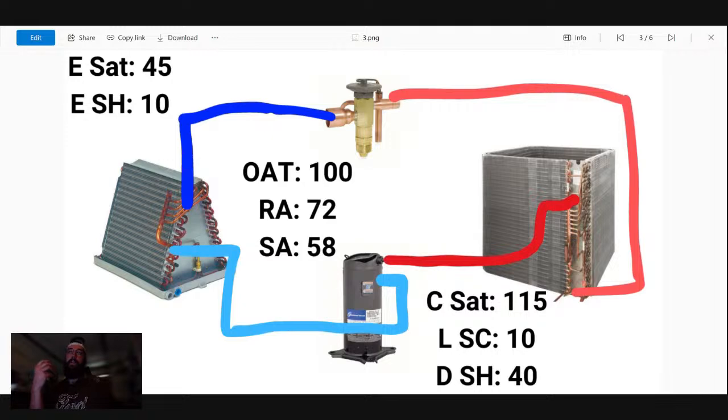So that's what he did. He moved the fan from low. It was originally on low. He moved it to high, thinking that was going to make it work better. And he thought that he did. But in reality, he created a humidity problem that didn't have to be there. So that's a fairly realistic scenario, in my opinion.